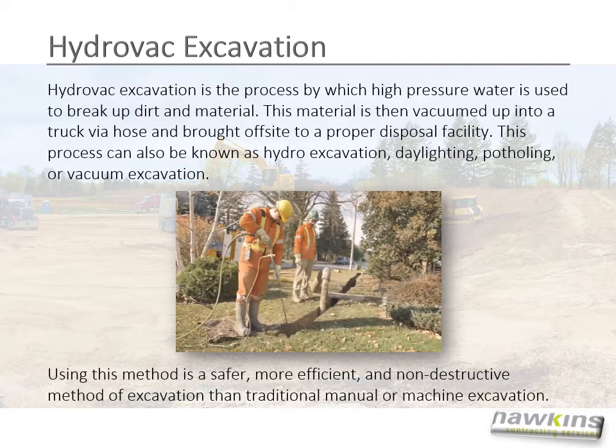Hydrovac excavation is the process by which high-pressure water is used to break up dirt and material. This material is then vacuumed up into a truck via hose and brought off-site to a proper disposal facility. This process can also be known as hydroexcavation, daylighting, potholing, or vacuum excavation. Using this method is a safer, more efficient, and non-destructive method of excavation than traditional manual or machine excavation.